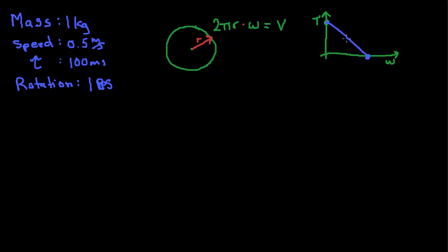So we can assume for a fudge factor that the robot will be operating about middle of the road, half of its no-load speed, which would be about here. So to get our desired velocity, we'll just assume that we're running at half of no-load speed, 1 over 2 no load.